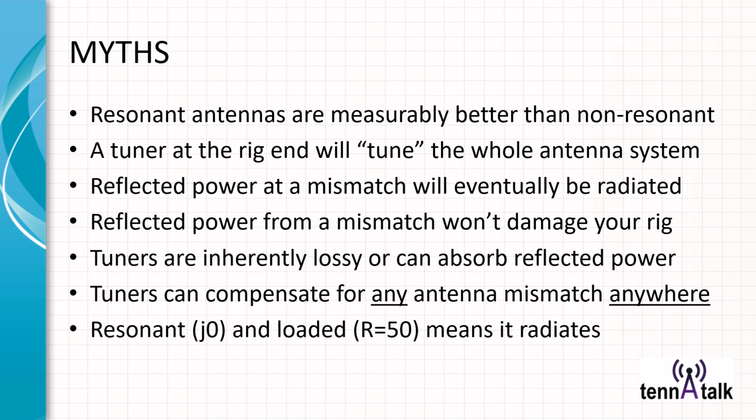So a few myths I want to wrap up with. Resonant antennas are measurably better than non-resonant. Not true. Non-resonant antennas that are well matched can easily be as good as resonant antennas, and sometimes even better, because they very often can be used on multiple bands.